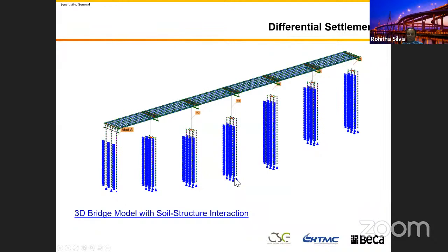We use the proper springs, and that incorporates the bridge deformations in here. But if you need, we can incorporate a predetermined deformation in the bridge, 20 millimeters, and we can check the deformation of the bridge.